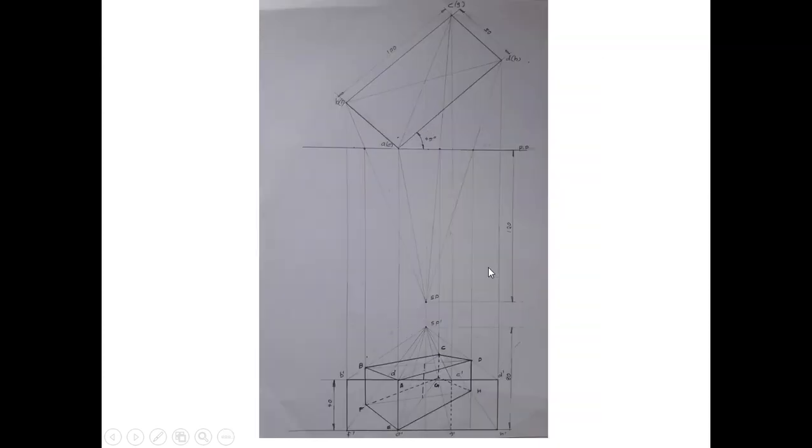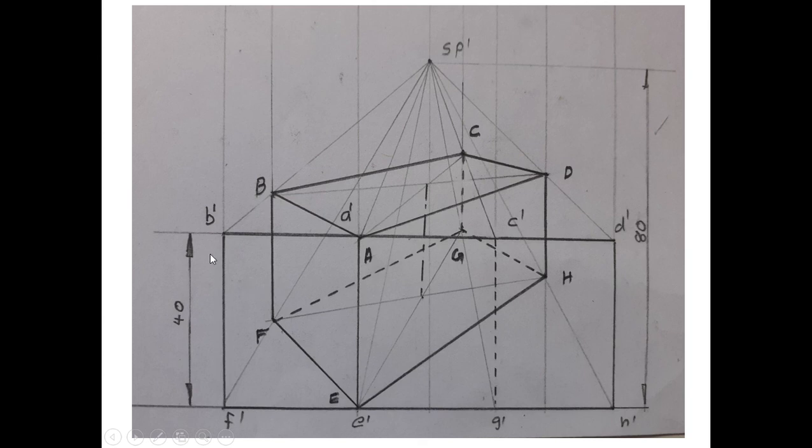This is the front view. This is the top view. And this is the perspective projection of the object. So this is the final drawing. Just darken those lines of the perspective projection, all those lines A, B, C, D, E, F, G, H and the vertical faces. Then slightly darken the names ABCD and EFGH, and draw the chain line. This is the final perspective projection of the object.